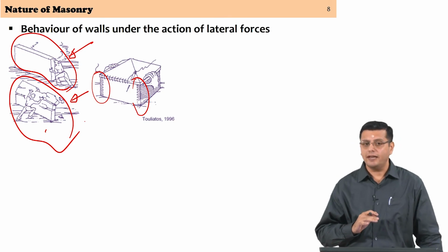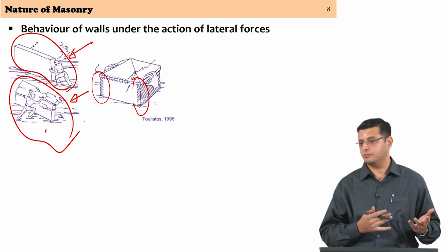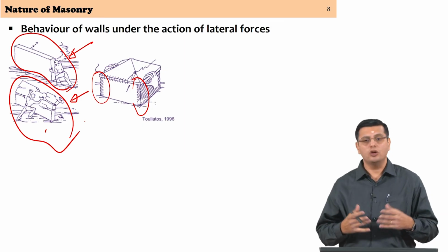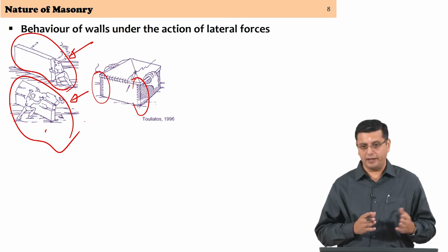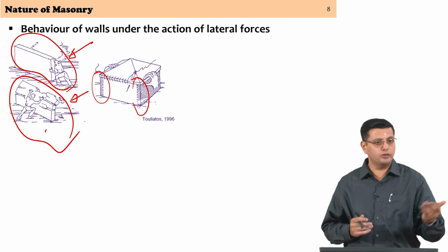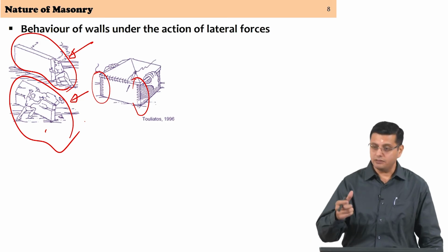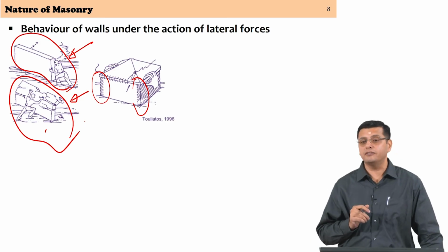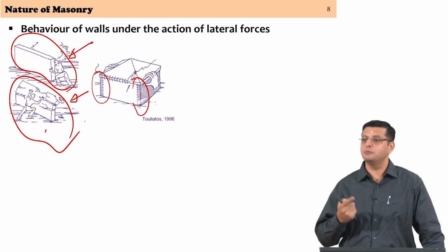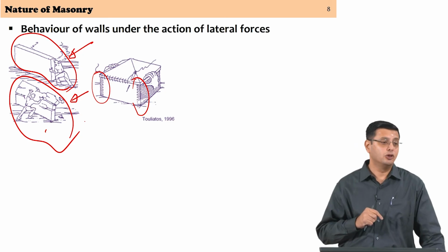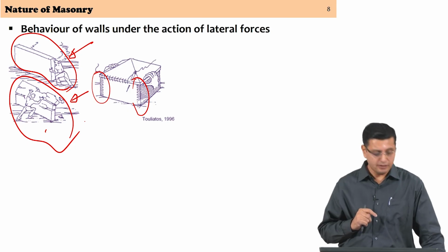So, what would you expect between the masonry wall subjected to in plane lateral forces and out of plane lateral forces, which do you think is more resistant intuitively? In plane, right? The cartoon there says you can even push it with your own hand in the out of plane direction, which of course depends on the stability in the out of plane direction, but it is very instructive to simply plug in some numbers to the strong axis and weak axis bending resistances, and look at in plane versus out of plane, is there significant difference between the resistance available in masonry.